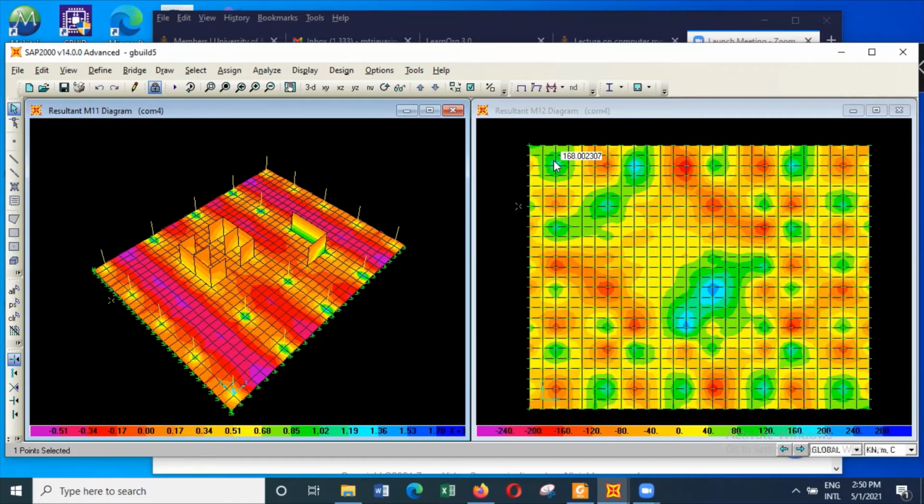when we looked at how to find where to provide the reinforcement when you use the finite element method, because you are getting a bending moment and a torsional moment, and how to interpret it. If the torsional moments are relatively smaller than the actual bending moment, then you can simply add the torsional moment to the bending moment.